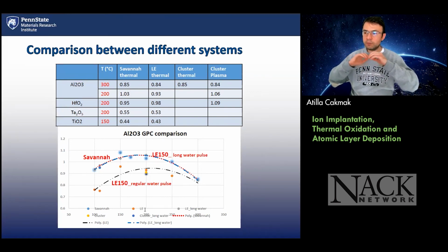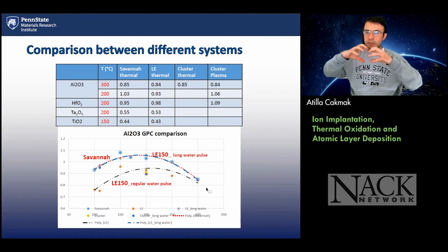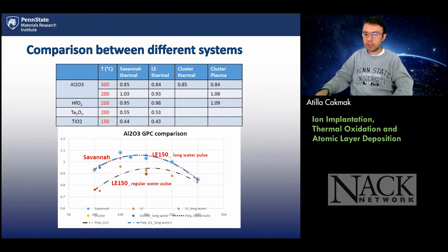What's the desorption? Well, if we heat up the surface a lot, like Rich has done, over 300 degrees, we're losing the growth rate, because the particle is heated up, so it can get loose and then get released, and so your deposition rate might be dropping down. So 200 Celsius is kind of the highest deposition rate, but you can also run it like Rich did at higher temperatures to make sure that even slower but more controlled growth rates can be achieved. So having said that, I will stop sharing.